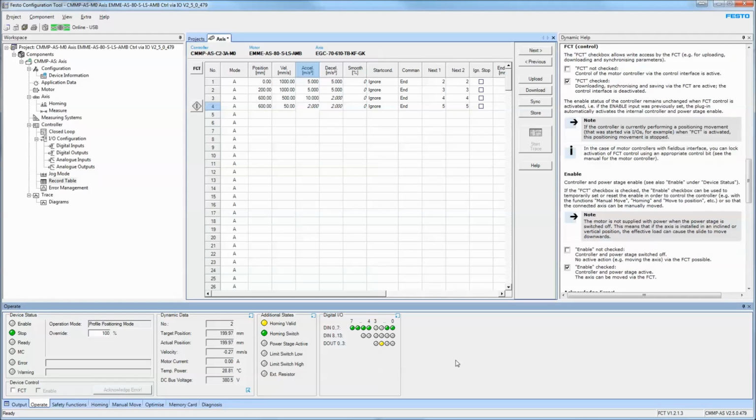Turn this back off, gain the access back through DIN 5. To execute record number 4, it's the next bit. And I'm going to turn the start bit on. It's going to start moving. I'm going to turn the start bit off. Now the acknowledge changes state again, and now we're waiting for the motion complete. Motion complete comes on when the move is finished. I'll do that one more time for you here.